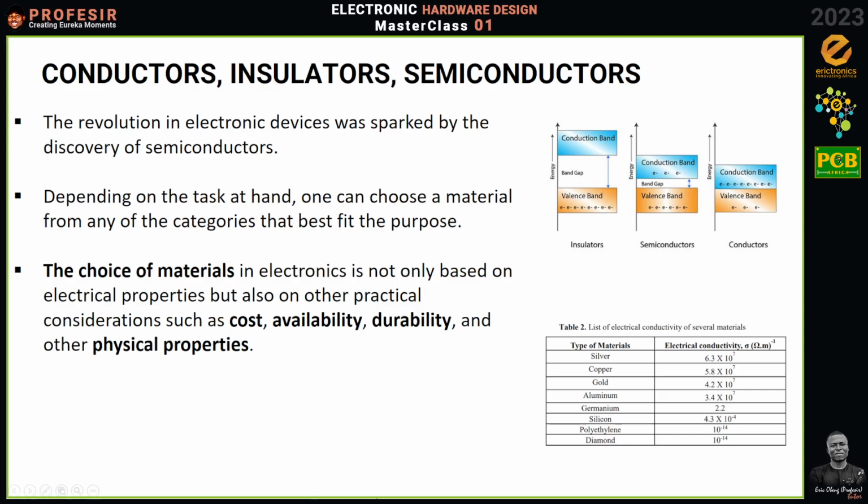Now, if you look at this chart of conductivity, you realize that silver has the best electrical conductivity. But mostly we are talking about copper. Every circuit, we are talking about copper. In fact, silver is scarcely used. Before you can see silver being used in an application, we really require a very superior conductivity, right? And mostly we are dealing with copper. Okay, so why is it so? It happens that you don't just look at the conductivity to choose the material.